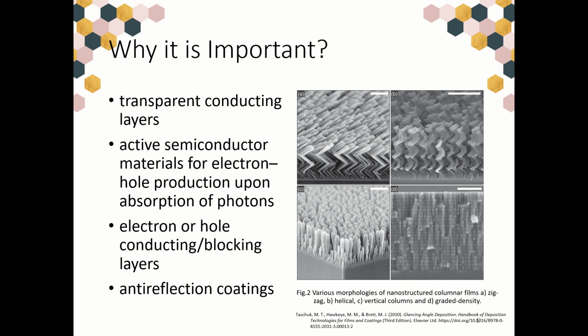First is zigzag structure, which is a film where the column orientation switches back and forth. Helical structures are created by high alpha deposition coupled with slow substrate rotation, a motion that continuously redirects the column growth orientation and shapes the columns into helical structures.